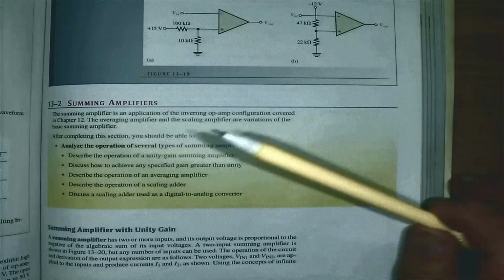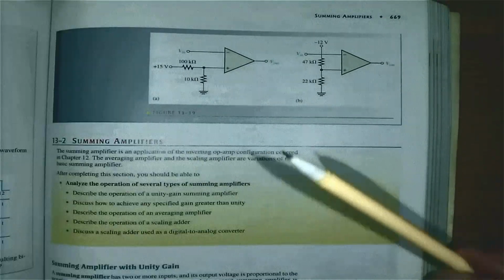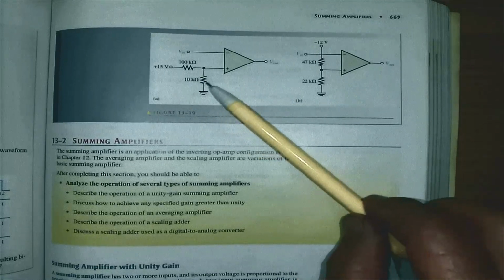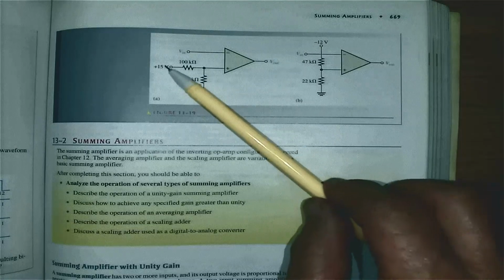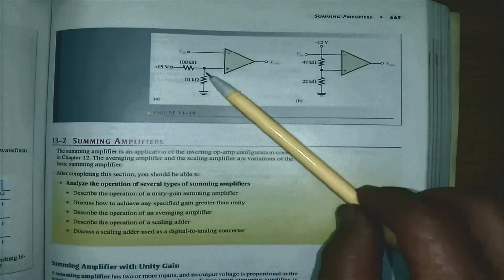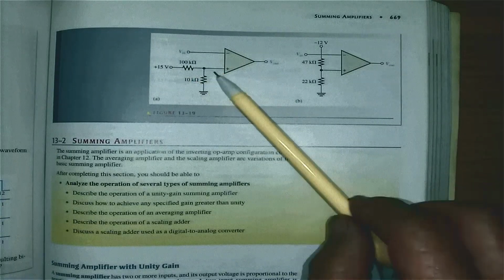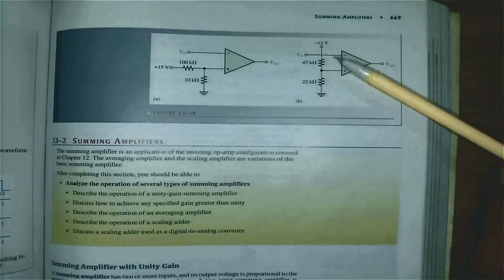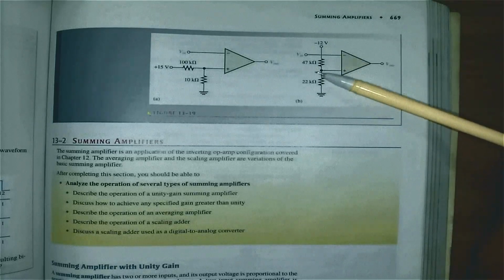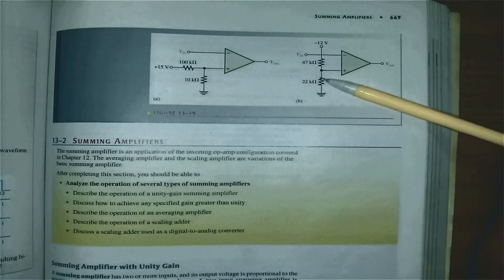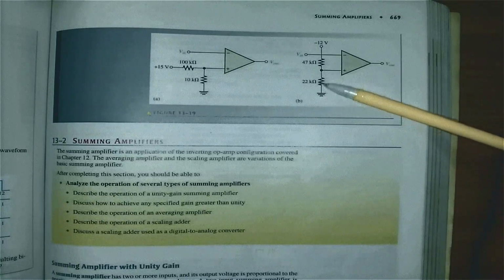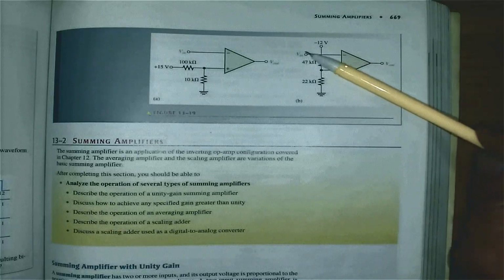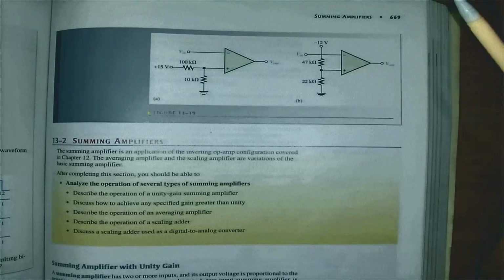All right, here they show us 2 comparators. First of all, here we see we got a reference voltage. We got a 100K and a 10K, and my voltage there is 15 volts. That means I will have a reference voltage, and the input voltage will be compared with the reference voltage. That means the voltage across the 10K. In this case, I have a negative voltage. That means my reference voltage will be negative, and that will actually be the volt drop across the 22K, which will be my reference voltage, and my input voltage will be compared with that. That means I will compare this input voltage with a negative voltage.